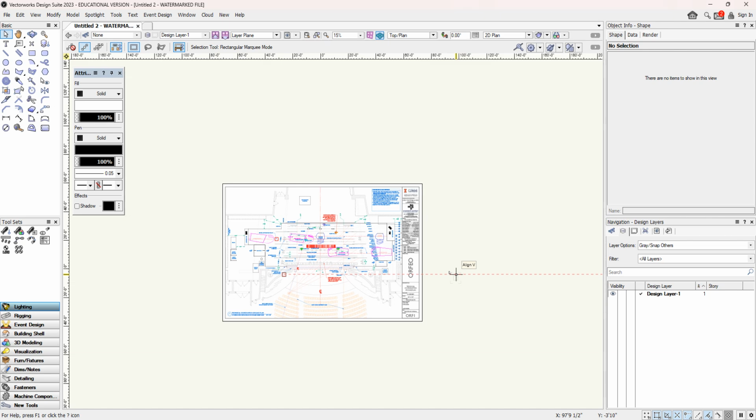If it's off by a lot, it might be really obvious as soon as you start writing numbers down. But if it's off by just a small amount, you might not notice until you have taped something out and it just seems like it's a little bit the wrong size or something. So please always verify the scale and the 0 before you start taking those coordinates.